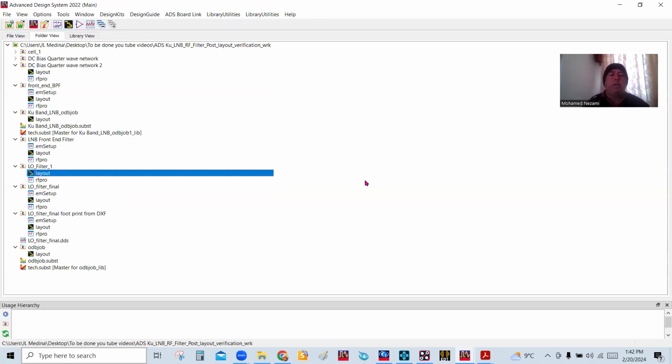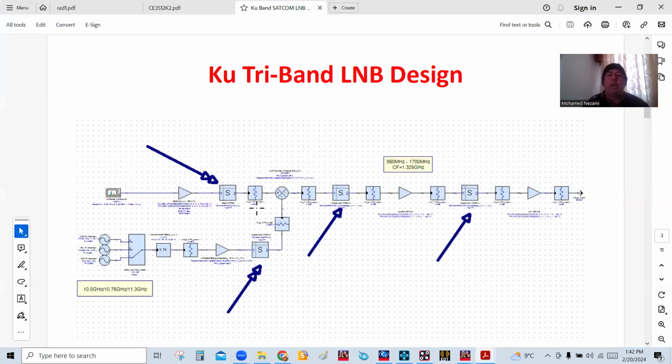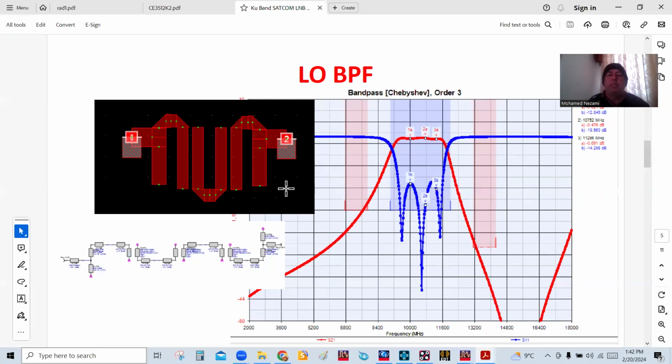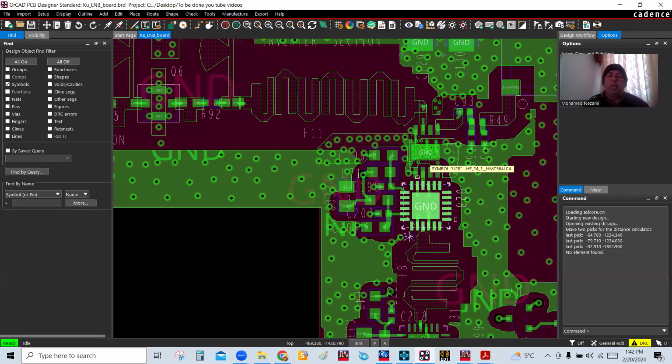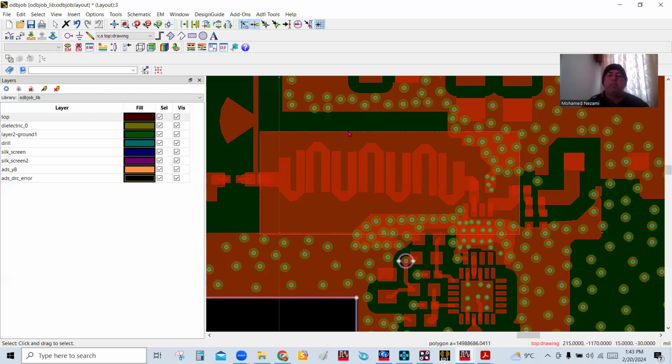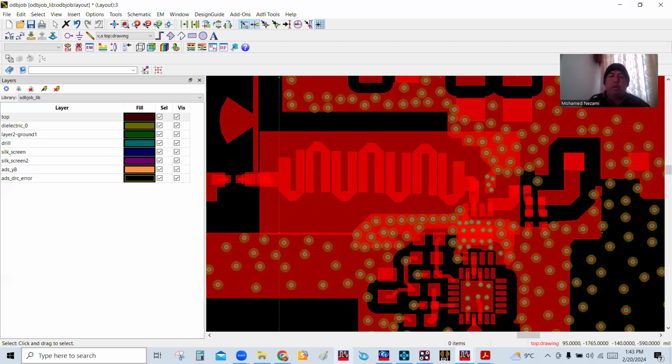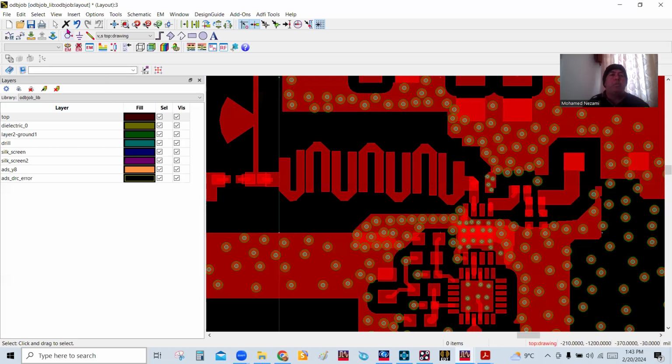ran this, and we went ahead and analyzed how this filter behaves compared to the performance that I got from the microstrip bandpass filter synthesizer in the Genesis tools, where that filter was designed. So basically, you take the artwork in here, and you do EM analysis on it when you import it into the ADS tool to try to see whether the information is preserved or not.